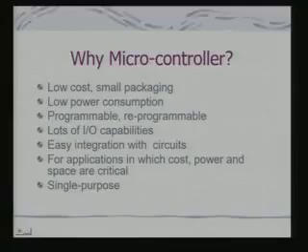And foremost, as I already stated, since I am having single purpose usage, I can manage with less sophistication on the processor hardware itself. That's why I have other peripherals integrated onto it, get a complete system with a small footprint, with smaller power consumption, and that's basically the reason why I go for microcontroller for embedded system design.